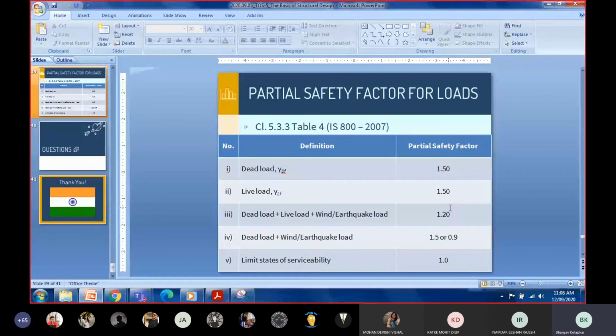You are going to care about your comfort only under normal conditions of the structure, not when it is about to collapse. So that is why we take care of the serviceability, we take care of deflection, we take care of vibrations, fire, and so on under normal conditions. So the structure should be serviceable at normal loads, and it should be safe at ultimate loads.